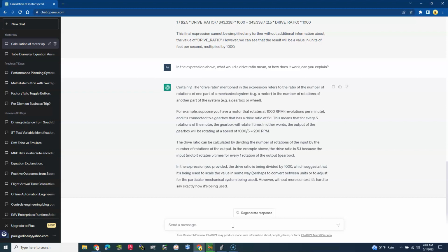So if the first one, which is the end, drives too fast and you're pulling paper across it, and it's actually pulling that paper, if it goes too fast and the one behind it goes too slow, you'll rip the paper. If the front one's going too slow and the back one's going too fast, then you'll bunch up the paper. The front one will not be pulling fast enough.